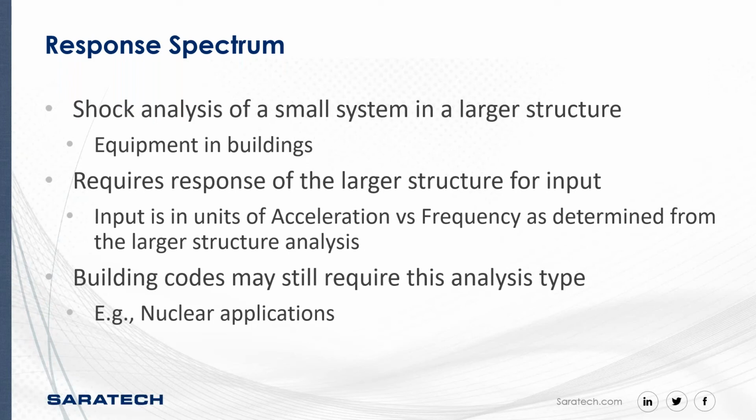That input usually is in the units of acceleration versus frequency, so meters per second squared, or in terms of G, versus each frequency. But this is always determined from the larger structure analysis.